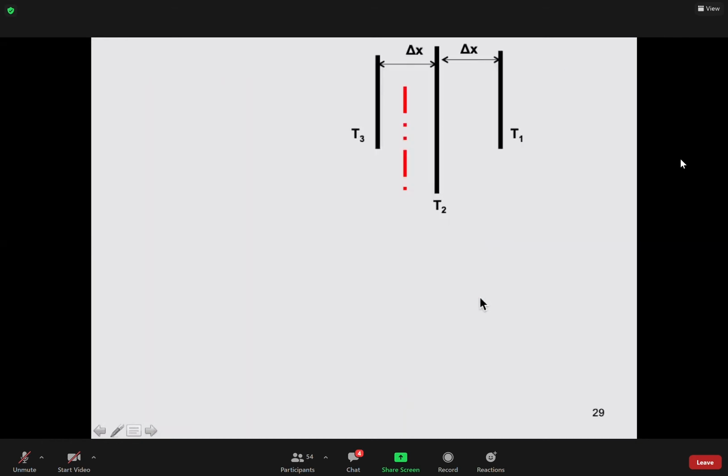Would you say M1 is the mass of the outer surface of the wall? As I mentioned here, sir, M1 is the mass of this layer of the wall, not the whole wall. When we discretize, when you select the number here, let's say delta X, node number 1 is at the exterior surface of the wall, node number 2 is somewhere inside, let's say 10 centimeter, and here is 20 centimeter. Therefore, the distance from this node to this node is 10 centimeter, and from here to here is 10 centimeter.